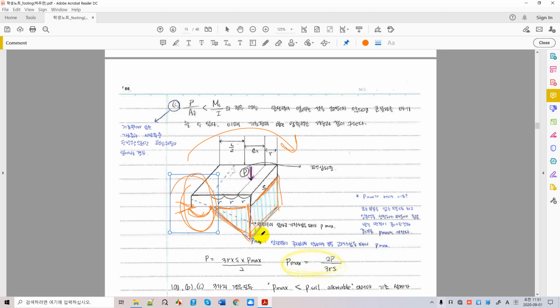Now we really need to know the soil pressure in this particular region, in order to compare it with the allowable soil bearing pressure. If the allowable soil bearing pressure is still greater than this soil pressure, then we're okay. Otherwise, we have to do something else, such as increasing the foundation's size or reinforcing the soils underneath the foundations, or whatever is appropriate to provide appropriate soil support.